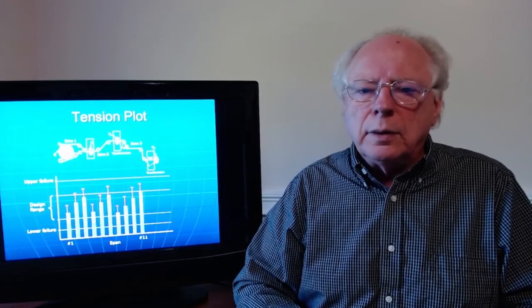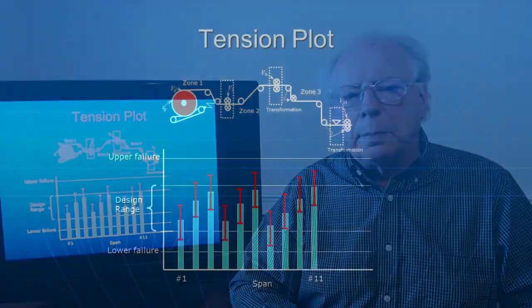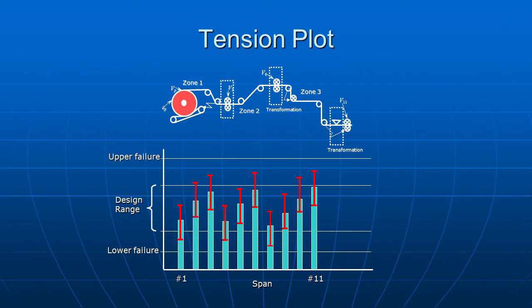And as you do this, you can pin some tolerance bars on your tensions. Now, hopefully, when you get through all of your what-if testing, none of your tolerance bars go above your failure criteria or go below your lower failure limit. If they do, now's the time to make the changes on paper and not do it in the machine after it's built. And so you can do all of the what-if testing that you want to do now, and all of the variation testing and all of the what-are-we-going-to-do-if-this-happens testing at this point.